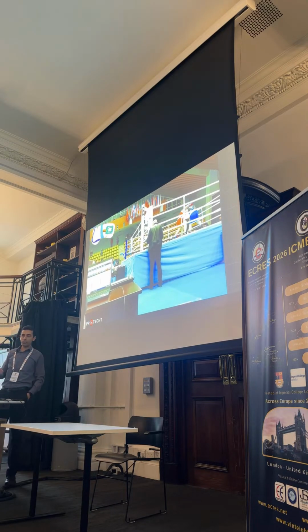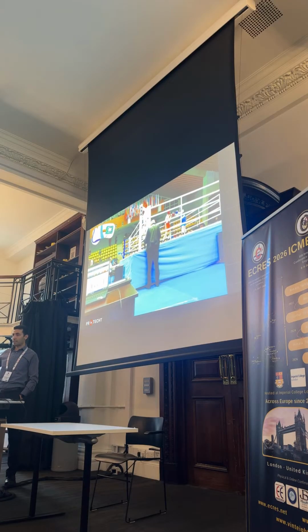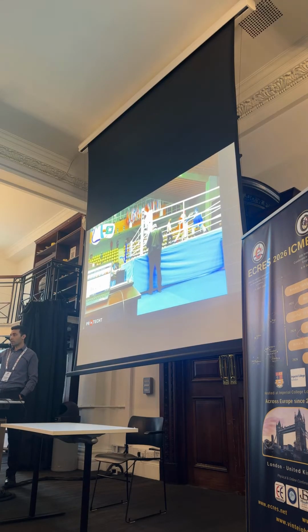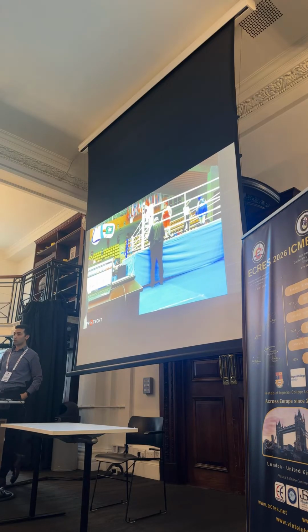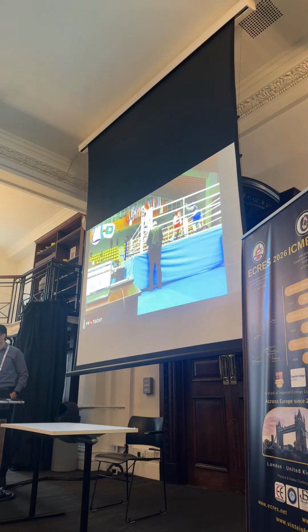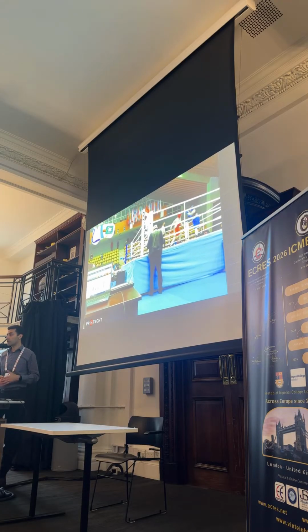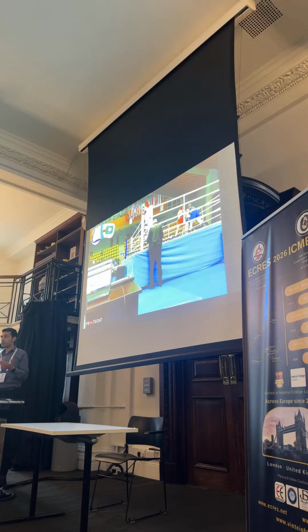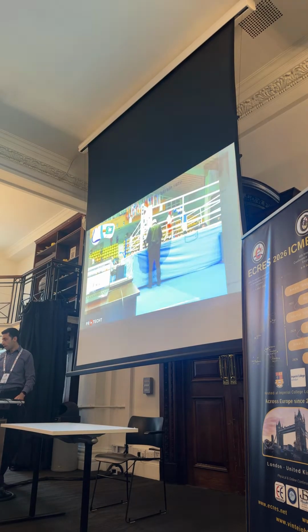Okay, so now we have the kinematics in real time. We can apply it to a brain model and get the results. But the problem there is that these brain models take around 4 to 6 hours to run on high performance computing, because they have around 3 million degrees of freedom, and then we need to run it for 100 milliseconds. This is an explicit solver we are using. The stable time step is around 500 nanoseconds. So you can imagine the number of loops that it has to go through.